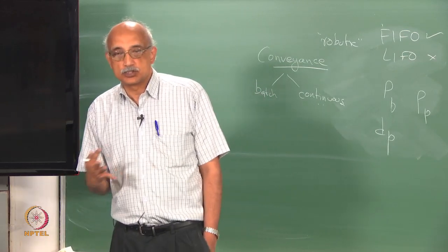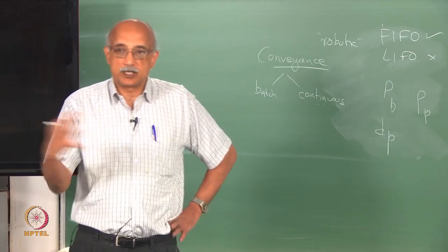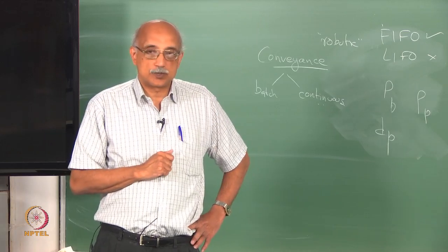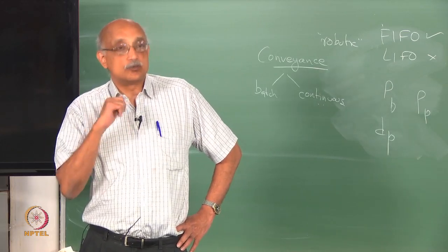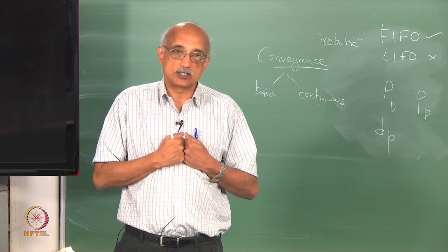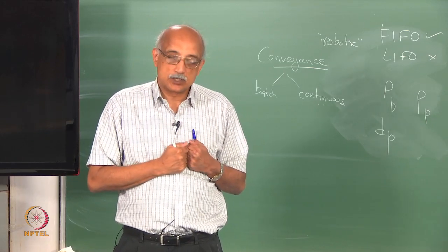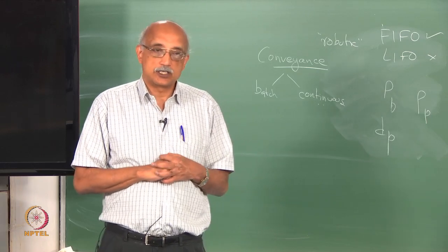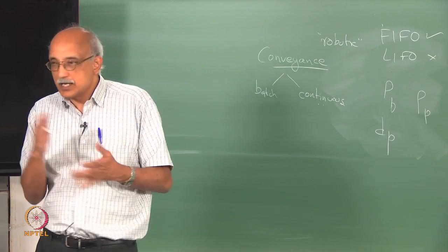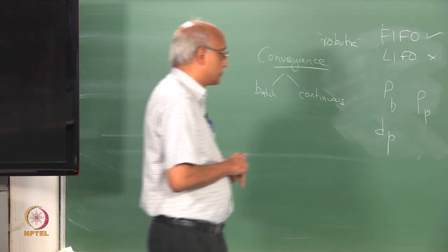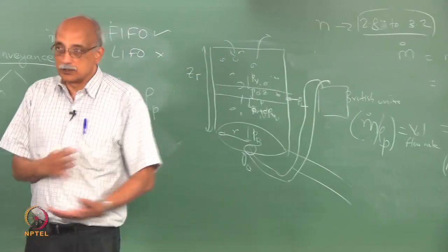It's very, very difficult to do, because as I said before, pumps rely on developing a pressure to discharge the material, but solid slurries do not react to pressure the way liquids do. In fact, they can get more difficult to discharge as you increase the pressure, because you can press the particles against each other and cause them to lock with each other. So, you really do not want to pump liquid particulate slurries. So, as far as possible, try to use gravity to help you, or inclination. Make sure that even if you are not able to discharge vertically down, at least provide a slope and try to slide the material down that way.